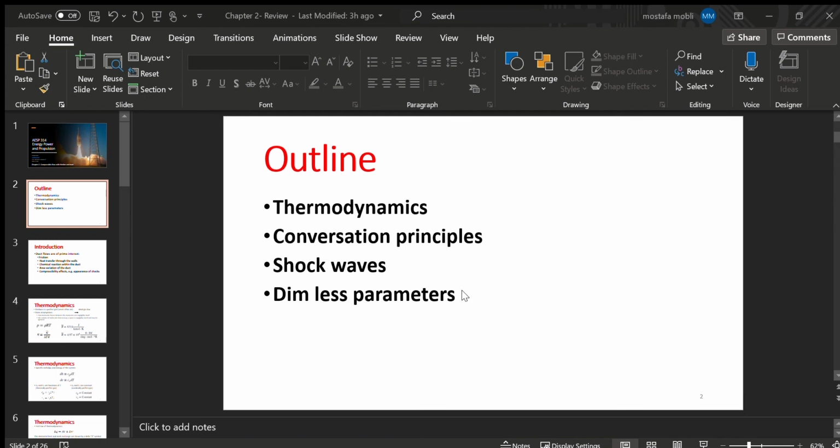And you can simplify this. You can just multiply these together, and simplify to get this equation: rho du is equal to negative u d rho, right? If you do the same thing for the momentum equation, this is what you're going to get. Do the simplification: rho u multiplied by u plus du, minus rho u multiplied by u, is equal to P minus P plus dP. Essentially, your delta P, the changes in temperature and in the pressure. Very easy to simplify. If you simplify it, this is what you're going to get: rho u du is equal to dP.